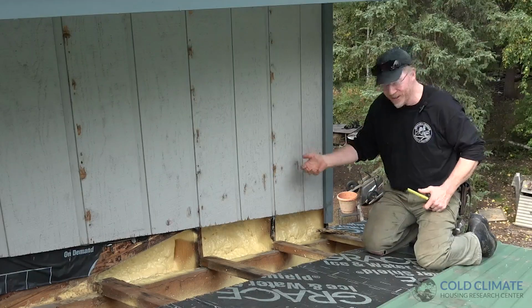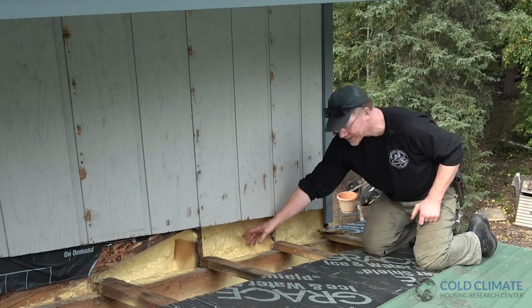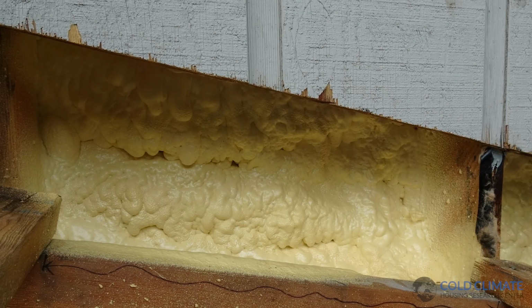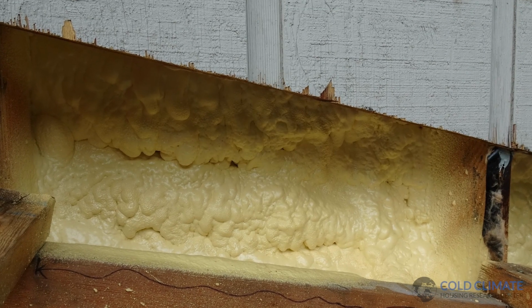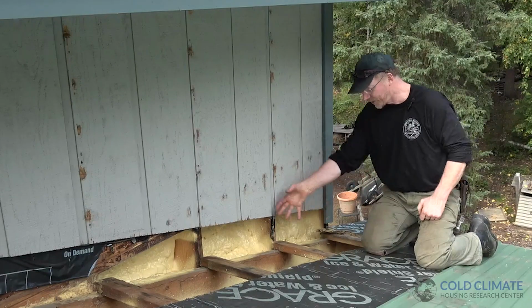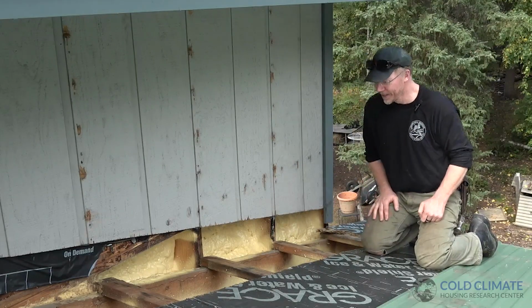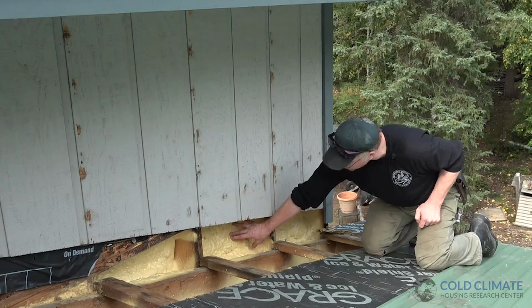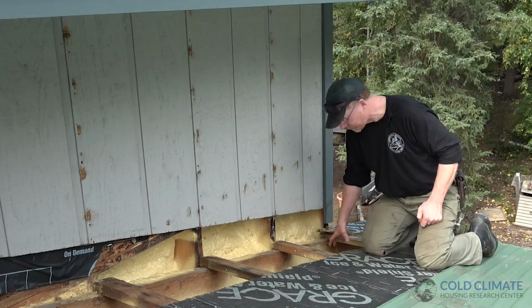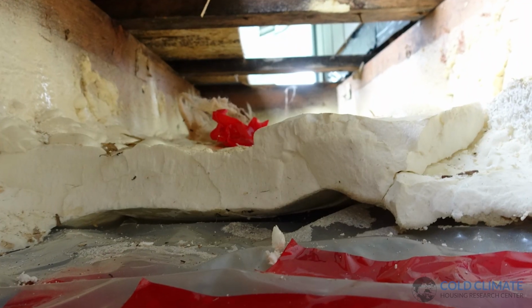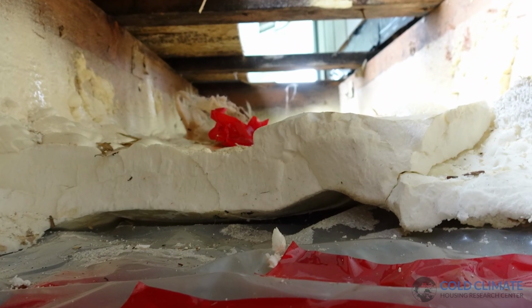And so we know historically that there's been condensing events in here, and this foam here is one of the attempts that was made to try to air seal this bathroom wall to keep that moisture and air leakage out of this rafter bay. What I can see is that not just were these bays sprayed, but there's also been 2 inches of continuous foam sprayed up the entire length of this rafter bay in an attempt to air seal it.